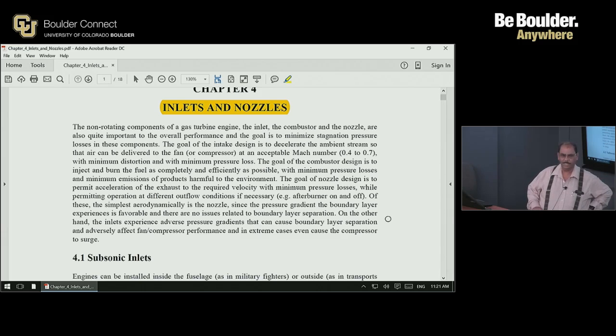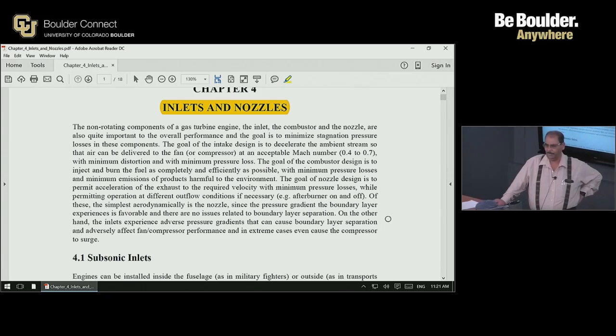There are issues involved, such as minimizing the additional drag involved in mounting the engine on the aircraft. Whatever that installation is, under the wing, in the rear, above the wing, whatever the case may be, the installation produces additional drag. Okay. The engine has to be enclosed in a nacelle, and of course the nacelle itself will produce a drag, both a pressure drag as well as a skin friction drag over the nacelle. Okay. That is one. Secondly,